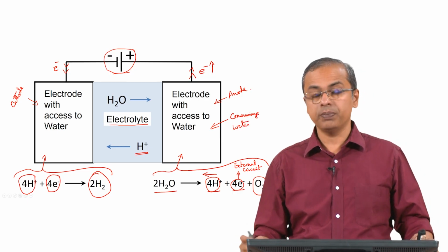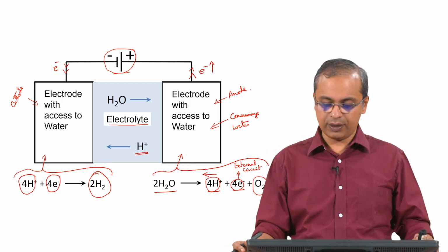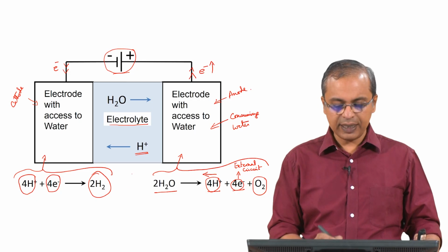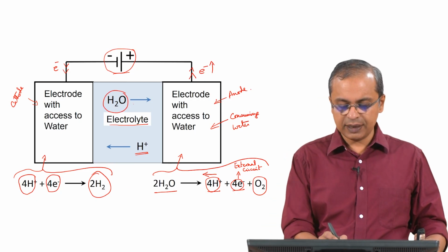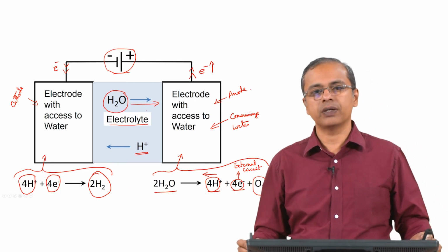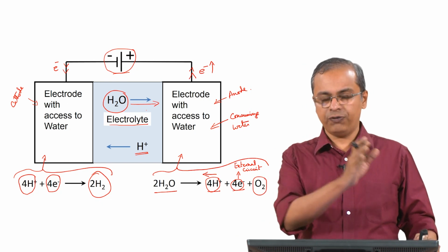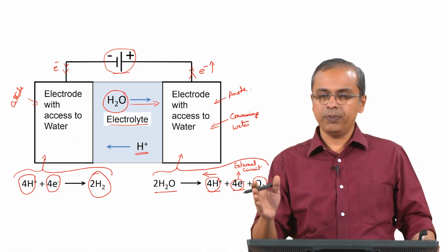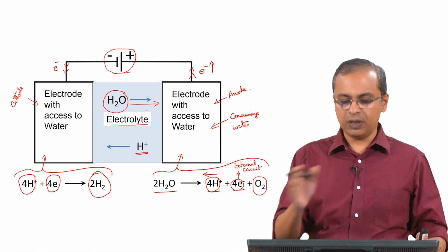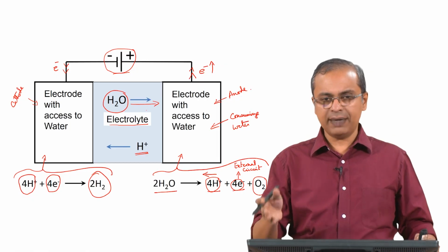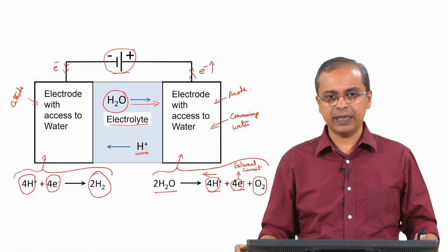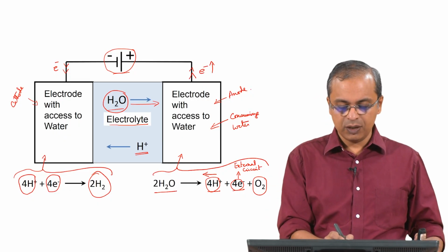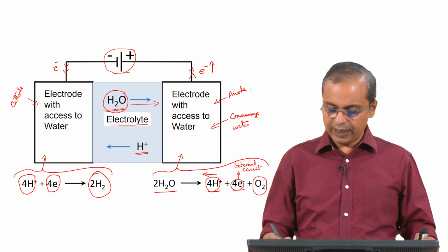So, water is getting consumed because it is getting split into hydrogen and oxygen. If you supply water on the cathode as well, that water will just transport itself across, the way I have pointed out here, right. So, you have a movement of water from your cathode to the anode, and movement of protons from the anode to the cathode. All this is happening, and of course, you can keep supplying more and more water to the anode side, so that it is not only dependent on the water that is coming here. It does not have to depend only on this water, you can directly supply water.